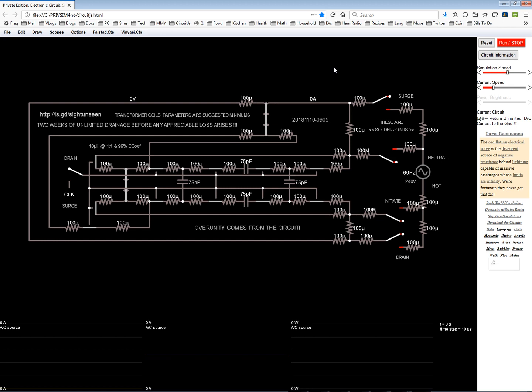or divergence errors. I think it's convergence. You look up convergence, and you look up the error in the error file, and you'll find they talk about divergence errors, even though you have to look up convergence to find it. And they actually admit that they monkey with your output, and you don't even know about it. The circuit doesn't tell you. They just tell you in the help file, if anyone's going to look. And Microcap is the standard in the lab section of electrical engineering at, I believe, Manitoba University